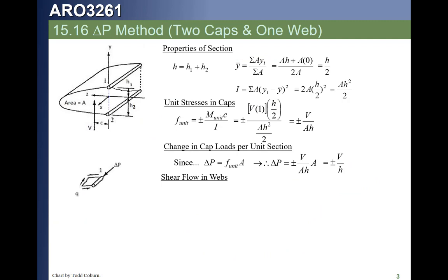Continuing on, we now can draw a little free body diagram. What we're doing here is taking a little infinitesimal piece. We're going to focus on a little piece right here, and we can say, if the shear was applied at this end, then there's no axial load in the piece here, but at the far end we're going to have that force times this dimension here, which we said was 1 inch, and that is what this little reactionary force, that delta P over here, is. Right? That's what we just calculated. This is giving us the delta P there.